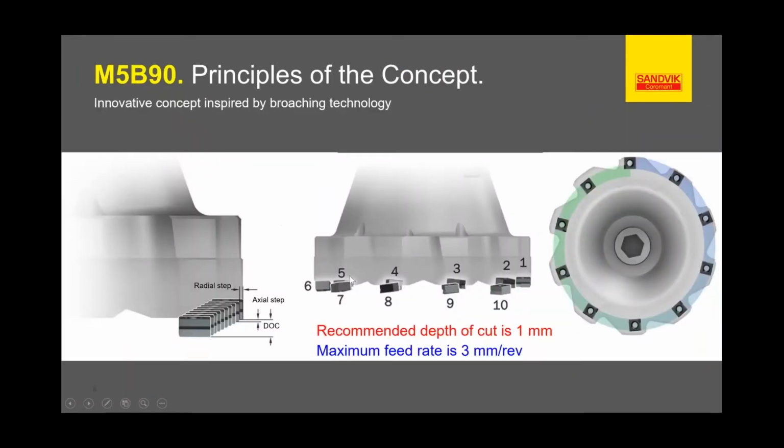So here's another look at it. Again, 1 millimeter depth of cut. The feed per revolution is roughly around 3 millimeters per rev. So that makes it like a high feed insert, basically. The axial thickness is 0.1 millimeters. So the chip is 0.1 millimeters thick, but the feed rate being 3, it's 3 millimeters wide. So that's a little fine ribbon that you're cutting, just shaving material.